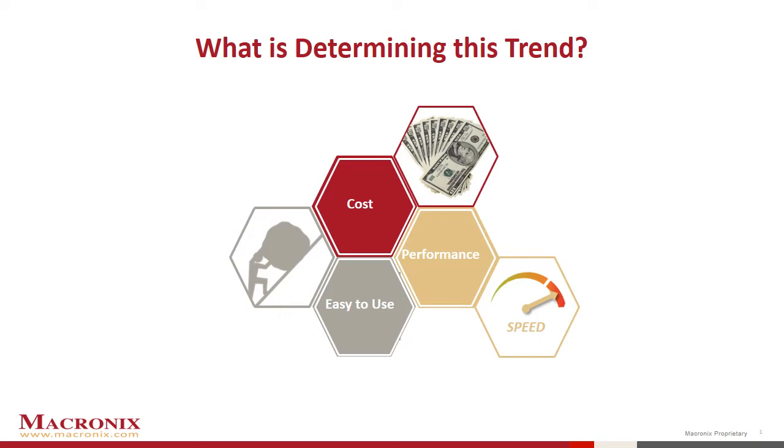Number two, performance. In today's designs, non-volatile memories are typically used to store code, and during system boot up, the code is downloaded to a RAM for execution. This is known as store and download application. Although NAND read performance is slower than NOR, it is sufficient for these store and download applications. However, there will be a performance penalty when using a serial NAND with on-chip ECC versus a serial NAND using host-based ECC.